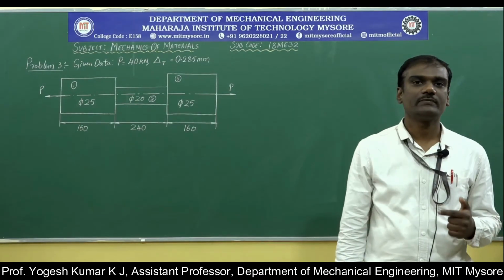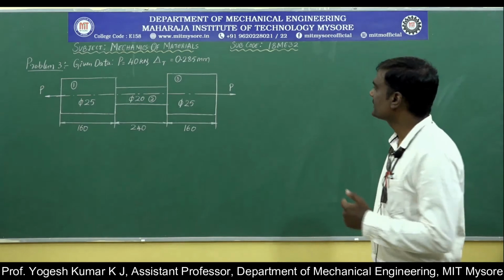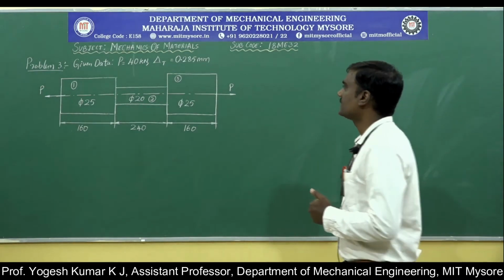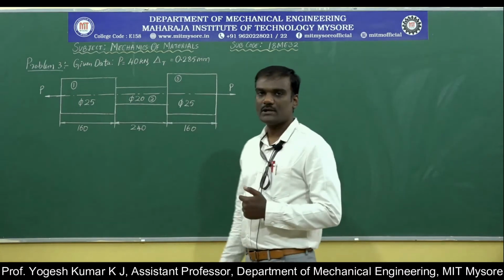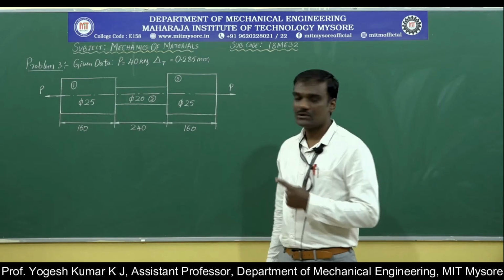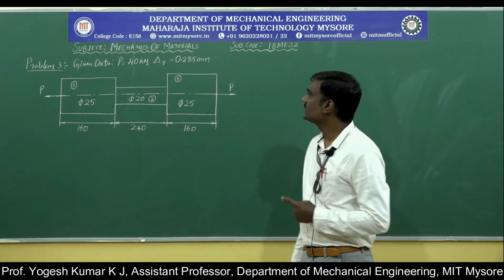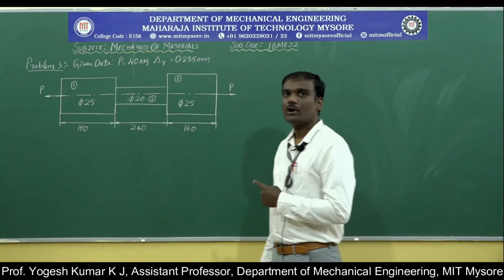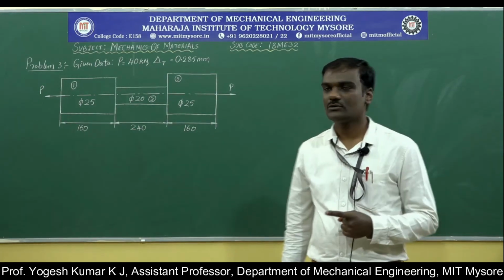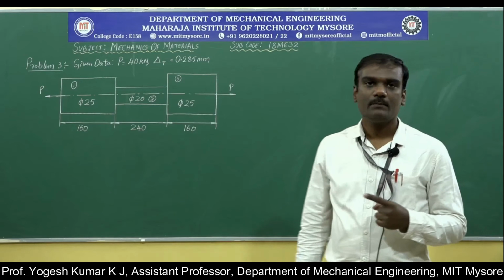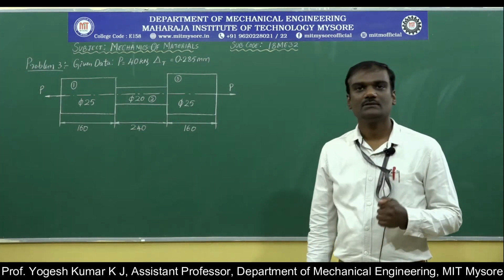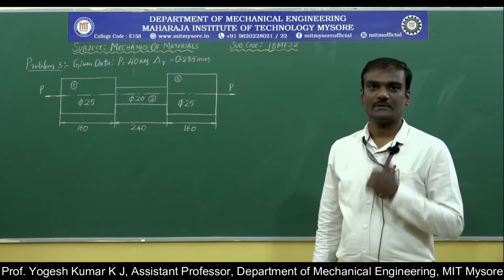It is observed that at a load of 40 kilonewton, the extension of the bar is 0.285 mm. Determine the Young's modulus of the specimen.